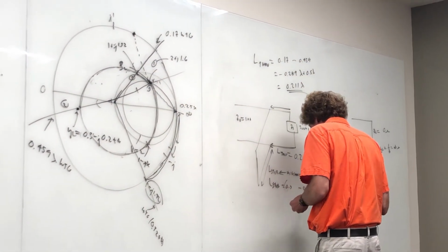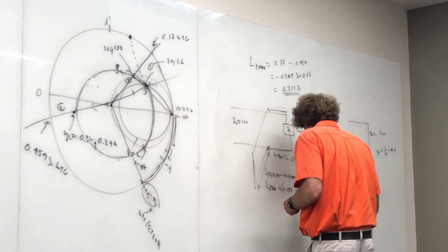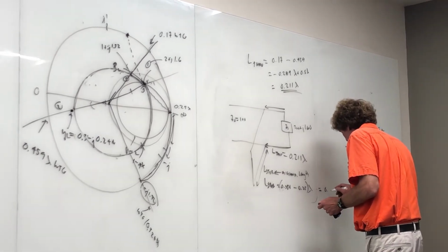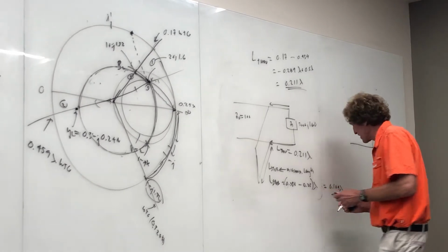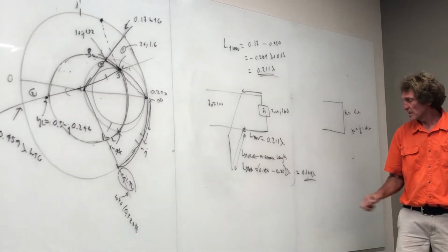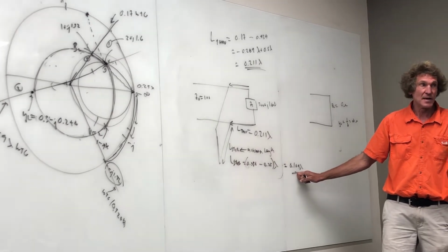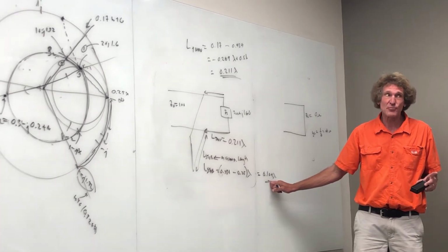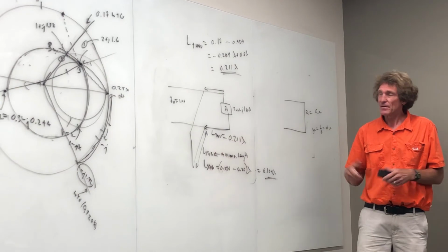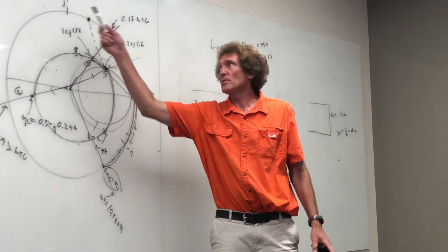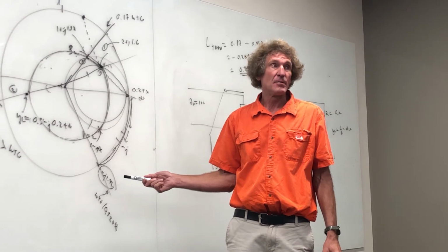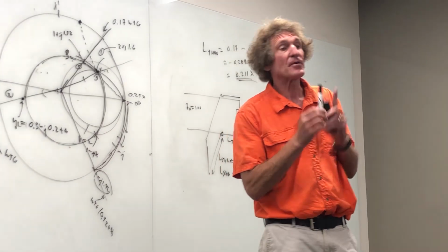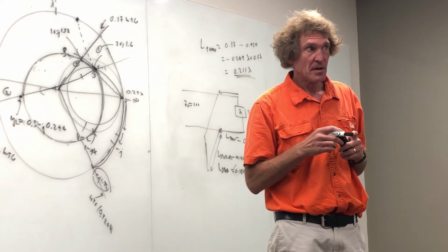So what would the length be? About 0.14, right? Isn't that about 0.14? 0.104 lambda, just barely inside. Now here's the deal in the real world. This has to be at least 1/10 of a wavelength. That's right at the border. The 0.07 lambda was too short to really use impedance matching techniques. You would have to go around the loop again, a full half wavelength, before it would be considered a true transmission line. In other words, the stub would have to have another half wavelength added on. Follow me, class? Are we there?